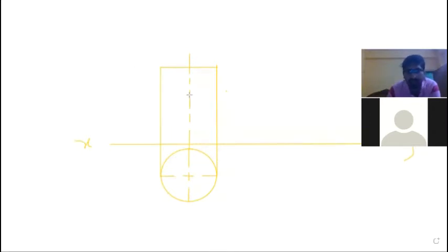At this point, first we draw a 45 degree angle, and this point height will be 35 millimeter. So this is basically the chain thin line, thick at two edges. Okay, so now what we'll do, here we draw. This height from the axis is 35 millimeter, and this height will be 50 millimeter. So from 35 millimeter we mark the point on the axis and draw a 45 degree line.